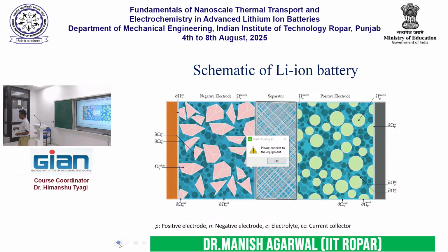If I start modeling each and every particle, and these are nonlinear partial differential equations, I have not gone into how you solve it. You have to discretize each particle with the finite element mesh, then apply Newton-Raphson, and then solve everything. You have to do implicit time integration and all those things. We are not going there. So it is going to be computationally a really big challenge to directly model whatever we have discussed.